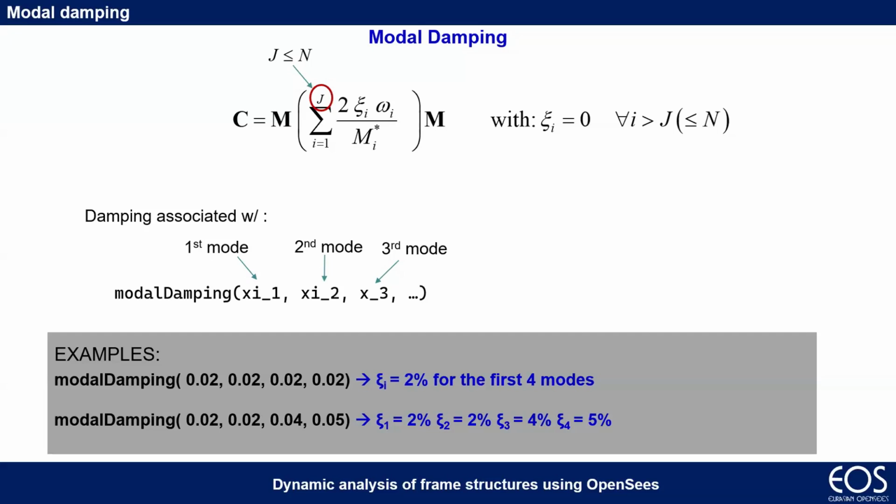There is a comment on Zoom: the stiffness to be used for Rayleigh damping has consequences in the obtained structural response. There is an excellent paper that explains this very clearly and provides a recommendation to select the appropriate damping model depending on your structural mode. Chopra and McKenna, 2008, unintended consequences. Thank you so much for the suggestion.